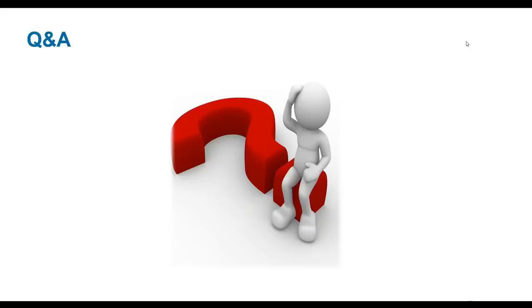It looks like I'm getting some kind of weird masking there. But basically when you draw a duct, there's an elevation setting, so you can put it at whatever elevation you want. If I want it to be higher, I just change the elevation accordingly. We can also set slopes. If you're doing piping and you want to draw a sanitary piping or something, you can set a slope and draw with the slope as well.